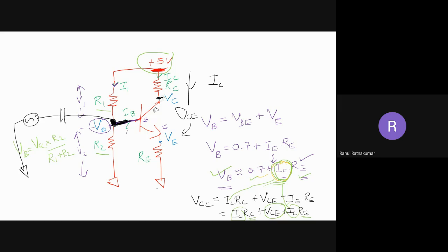So the small voltage I'm giving here will give a higher voltage here. If I need to take the output, I need another coupling capacitor, CC, and I can use some other block, like a display. So this is my next block, and this is the way I couple my AC to the next block.